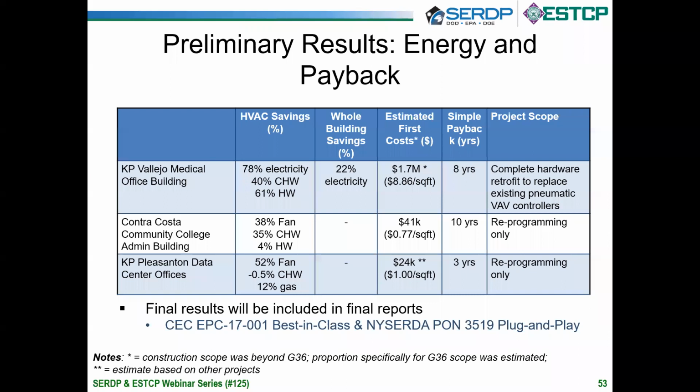So it was set up to make the building comfortable at 7 a.m. Well, the building operator, after the handover of the building, didn't fully understand that this sequence was in place and did what he typically does and said, I want the building to come on at 5 a.m. so that it's comfortable at 7 a.m. So a lot of operators just arbitrarily set the turn on time for a building, hoping and knowing that it will be comfortable by occupancy.